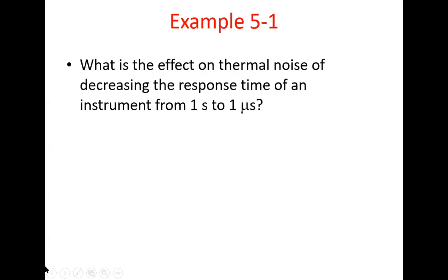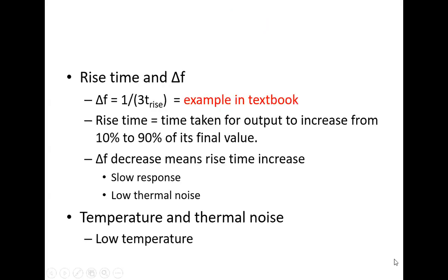Let's step back to our formula. The bandwidth, delta F, is equal to 1 over 3 times the rise time, right? So this rise time is related to the bandwidth, and the bandwidth, as you know, you get it from the thermal noise. Remember the formula?